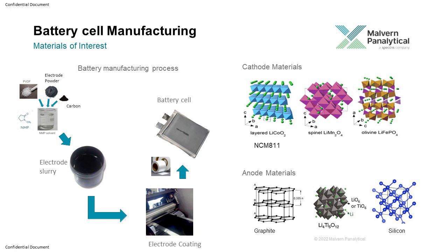Other is the spinel, which is LiMn2O4, but this is more for the smaller kind of batteries, not much used in the electric vehicles. In the electric vehicles, another chemistry that is in use is the LiFePO4, lithium iron phosphate. The advantage of this chemistry is that this has a better safety than the NCM. It is more stable kind of material. So from the safety point of view, when you have higher temperature and lower temperatures, this chemistry is more safe. It will not catch the fire.